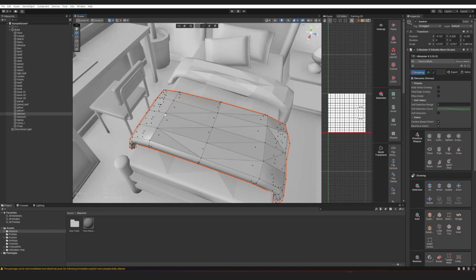After slightly moving the points up, down, left, and right, select all faces and click Clear in the Smooth Group to reset. This will create a surface with a triangular polygon pattern.